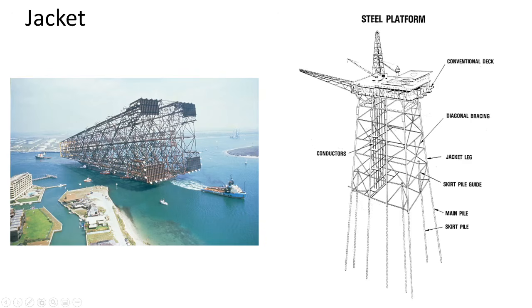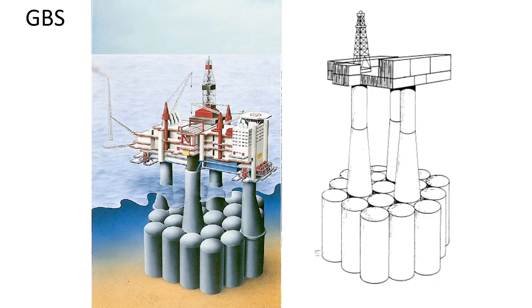They have the holes for the piles, and then they hammer them in place with a hammer that is simply driving the piles into the soil. And this is to make it stable, because this structure is heavy, but it could have some movement if you don't anchor it in place due to the marine loads.